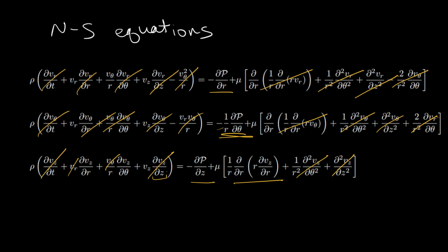And so first I'll take a look at these two equations here. This equation in the r direction, this equation in the theta direction. And so we find that dp dr is equal to 0. And note that we don't have any gravity in this equation, so this p is actually our dynamic pressure. So that incorporates the gravitational term in this equation as well.